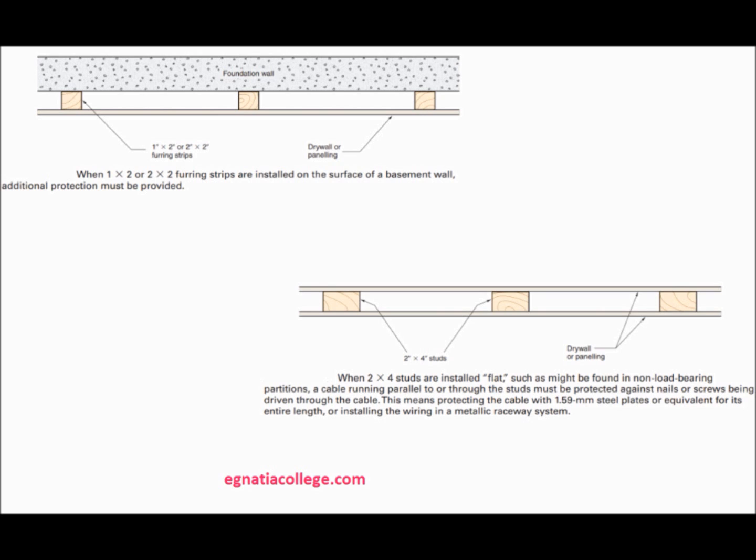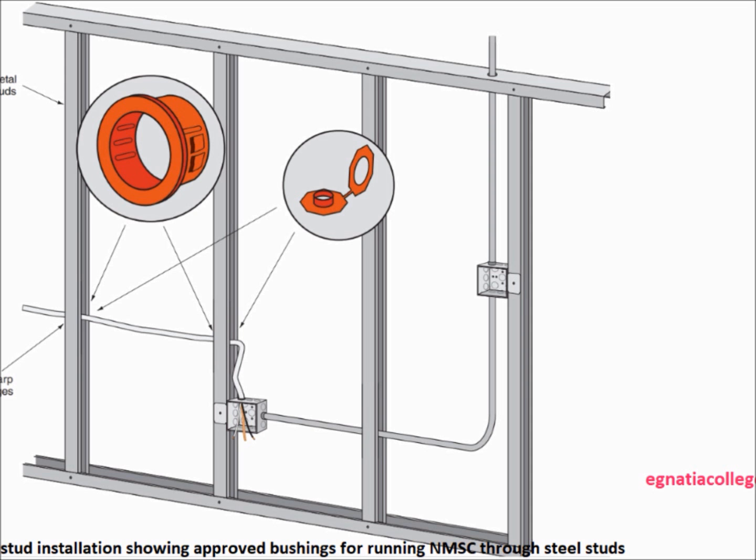Steel framing is used in a wide variety of residential applications, including single and multi-dwelling buildings. The framing is galvanized sheet steel that is pre-punched to accommodate the installation of electrical and mechanical piping and cabling. Steel framing is used for non-structural, light gauge, and structural, heavy gauge applications. When installing metal boxes on steel frame you can use self-piercing screws on light gauge framing, but self-drilling screws will be required on heavy gauge framing. A minimum of 3 threads should penetrate the framing.